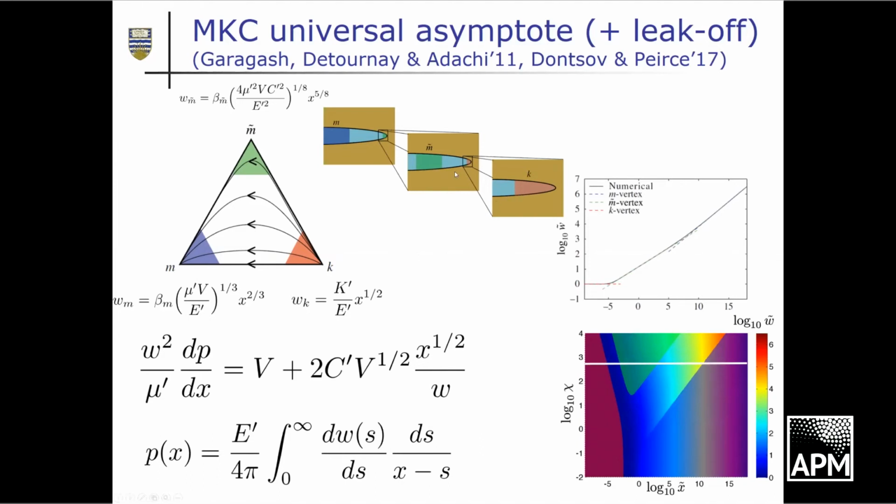So you get a sort of triple deck of asymptotics, three different asymptotes, all active in the same hydraulic fracture. And the trajectory as you go away from the tip is from toughness to leak-off to viscosity, as you traverse that.